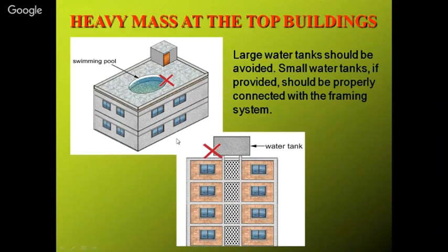So when the earthquake force comes, these columns will fail from here, and this water tank will fall on our building. Because of this water tank, the upper building will be damaged, and because of the additional compressive force and additional moments, the building can collapse.